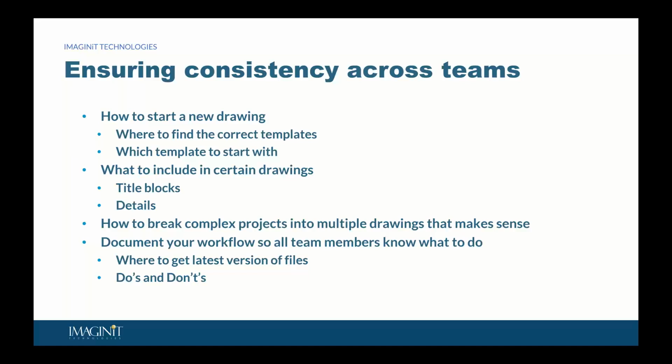I have seen some issues where you will open up a drawing and it will tell you that the surface needs to be renamed. You rename it and save it. Next time you open the drawing, it tells you it needs to be renamed back. That's a problem that I have come across, and it requires a little bit of effort for us to go through and clean that up, but just beware.